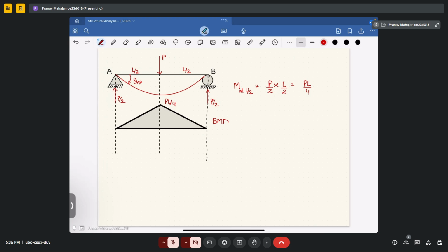So now change this bending moment diagram into bending moment divided by EI diagram. Okay, so suppose now I am extending this. I will make this diagram to be M by EI diagram. Fine. So how will it look like?